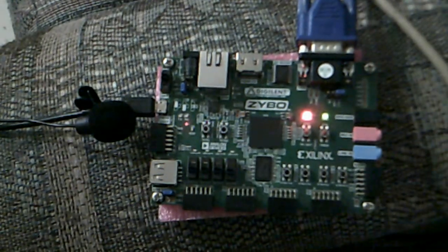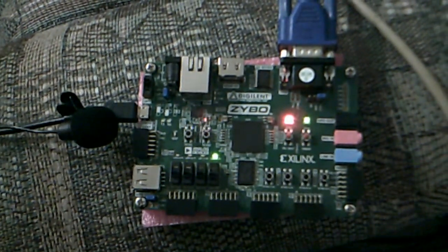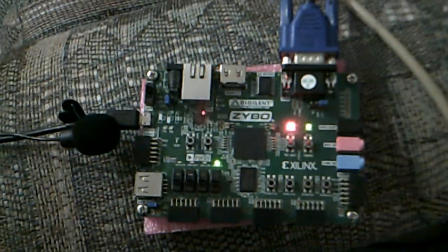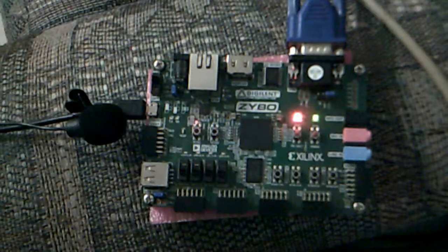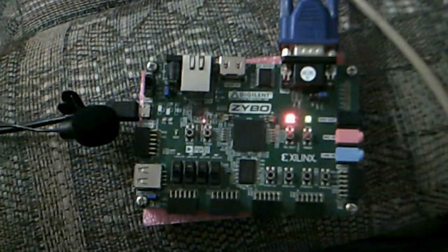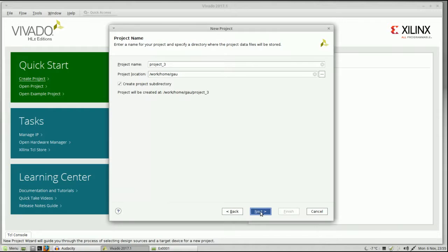Today's adventure is generating clocks in Vivado. Back in the VGA project, I mentioned that it was important not to make clocks with the logic. The reason being that the routing can generate different lengths, so the clocks do not get to all your logic at the same time, and as a result, you can get glitches and projects that just won't work. You'll wonder why. It'll be really subtle.